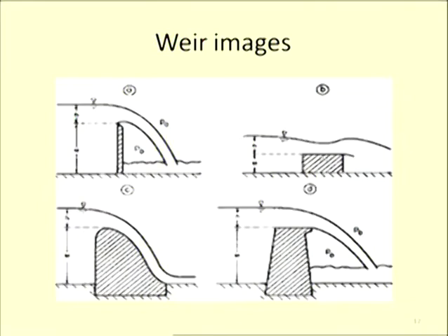You look at this, the breadth here is very large, from here to here, and the flow goes up with the increased depth and then joins the downstream side. This is a particular shape given. It's not like sharp-crested, but water is gliding. Here depth H is created because of the height of this weir.